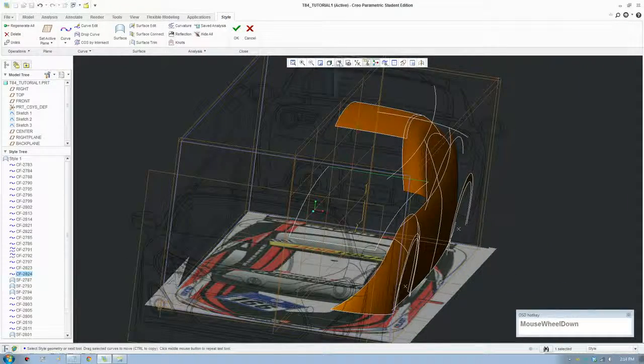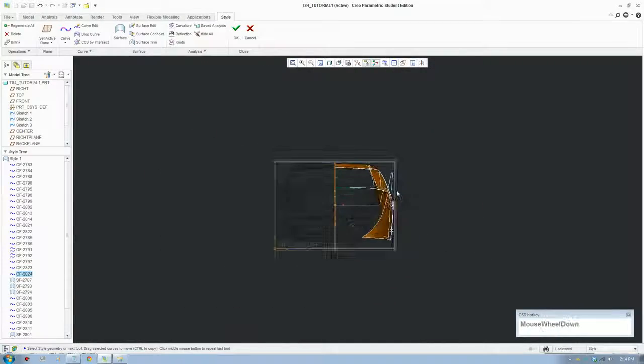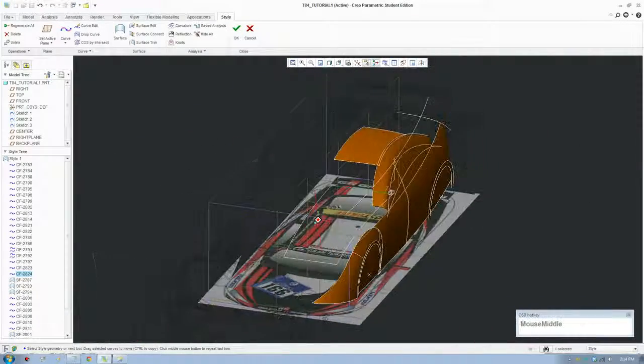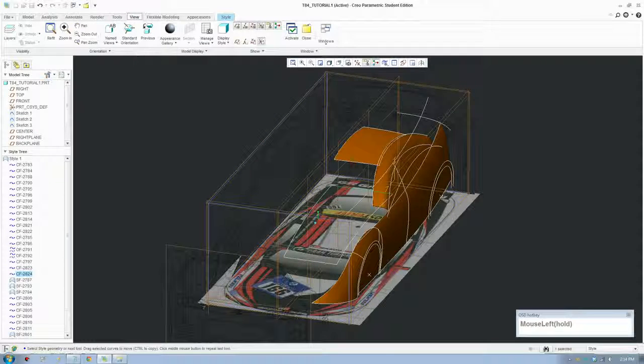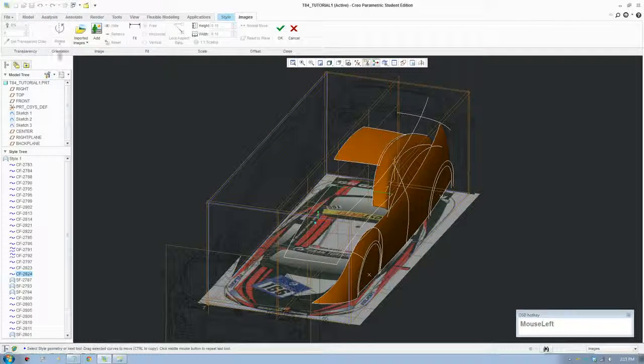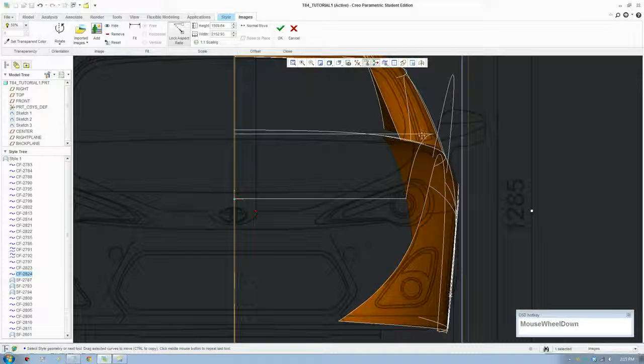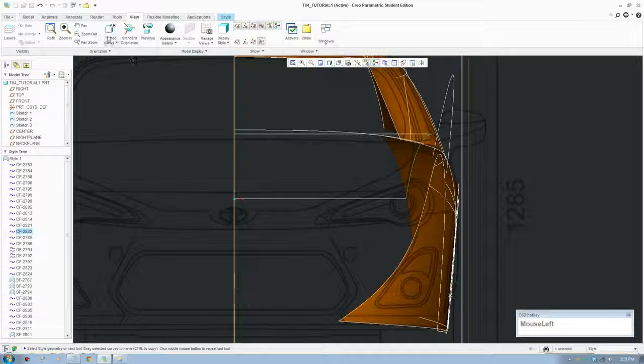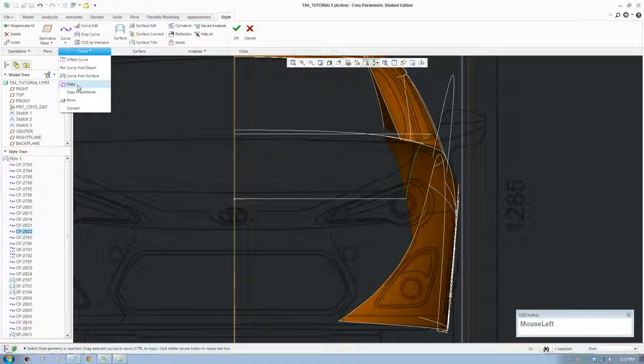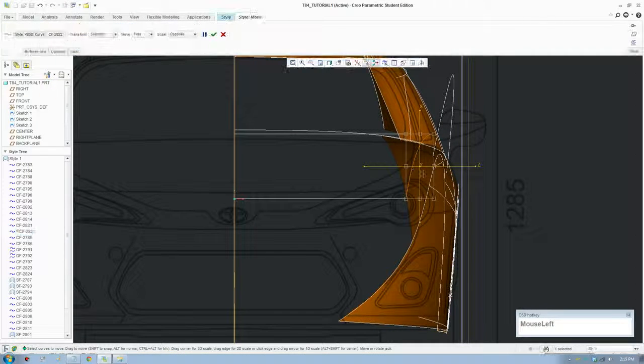And we'll switch to front view and we've got to hide the back. Go to images, we gotta hide the back so it's easier to see the front blueprint. Go to front view and just add a curve to this. Curve needs to go down slightly. Let's move that down. Go to move. Okay.